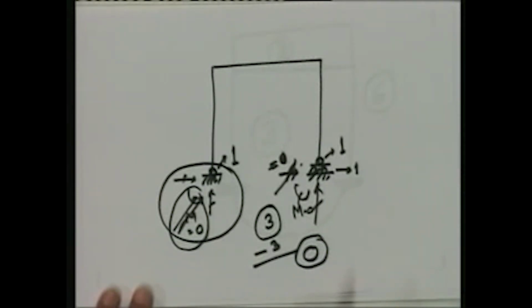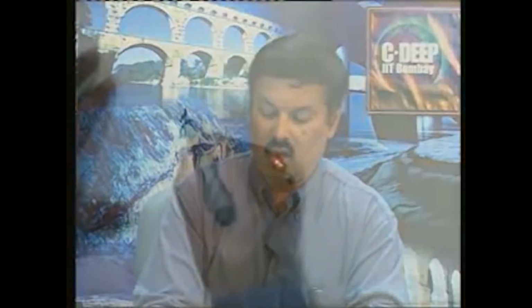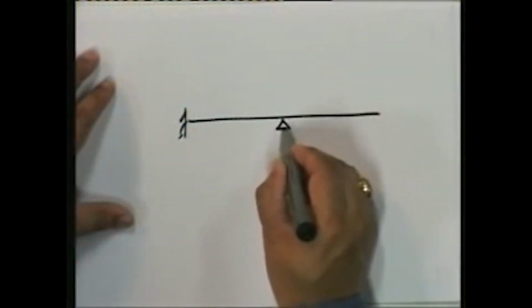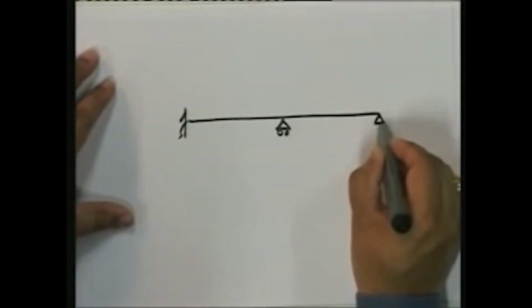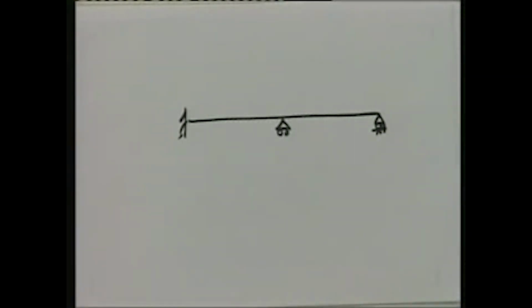Therefore, in planar frames, you essentially start off trying to create a ring. Well, let's now look at another structure. You might say, you're always taking a plane frame structure and trying to make it into a ring. Give me a multi-span beam and show me how you make it into a ring. Well, let me show. This is a typical multi-span beam. Okay, what's the degree of static indeterminacy?